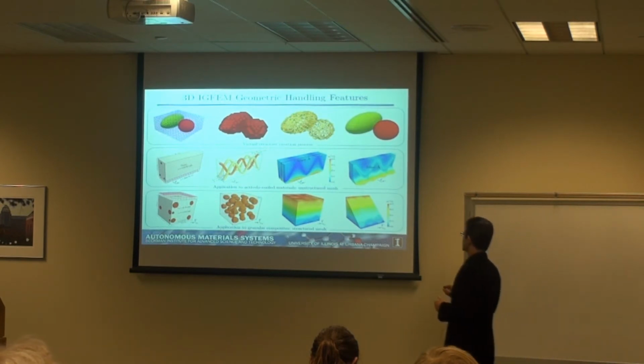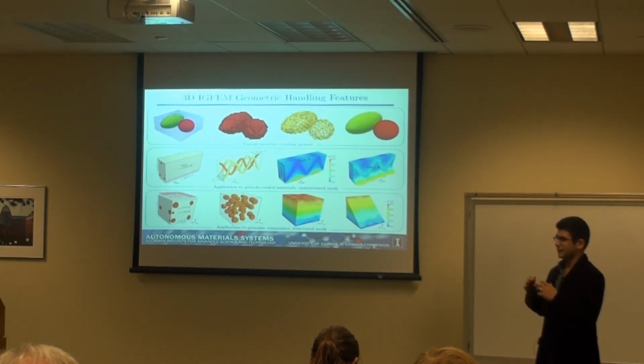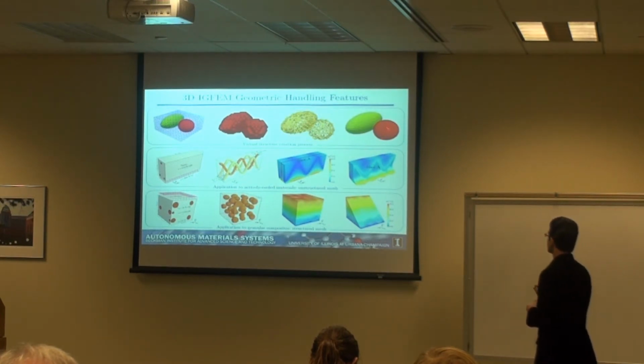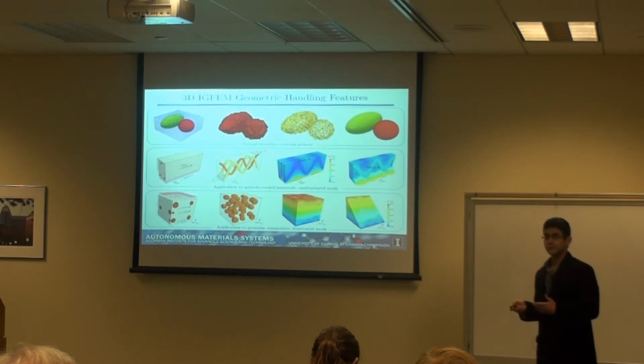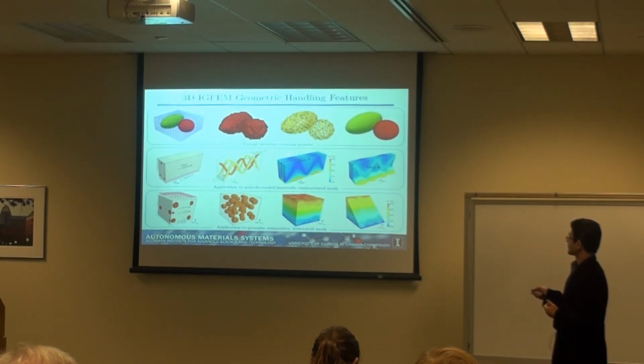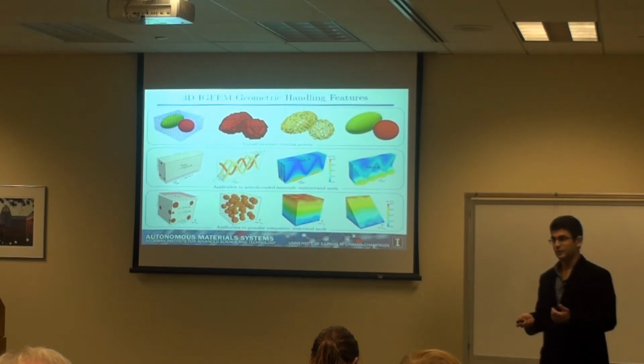Different steps are listed here to recognize geometry, doing some tessellation for recognizing the surfaces, and then finally creating nicely formed and smooth surfaces. So the main goal, as I mentioned, was to simulate actively cooled material. Here you can see the geometries created through that, nicely formed microchannels, and then the thermal response evaluated through this method. And as we tested the method, it was just as accurate as those conventional methods.